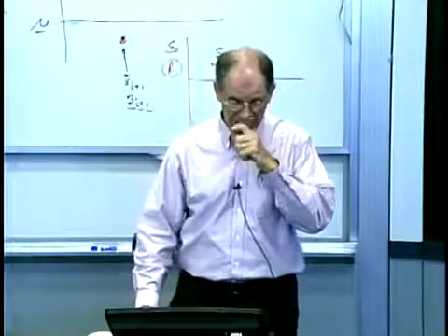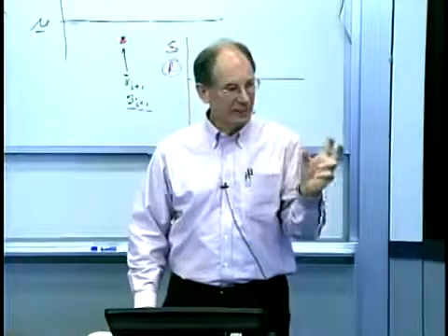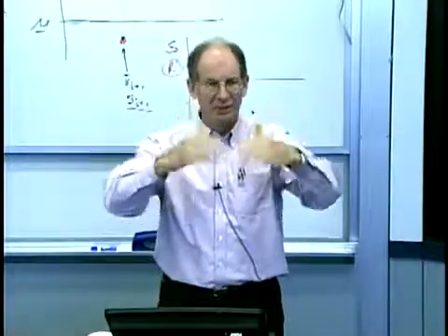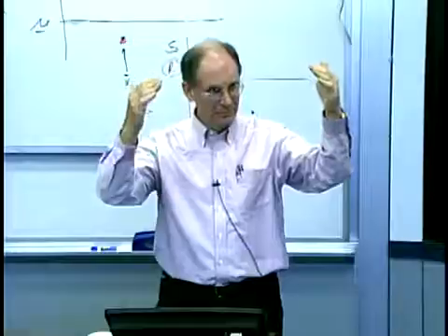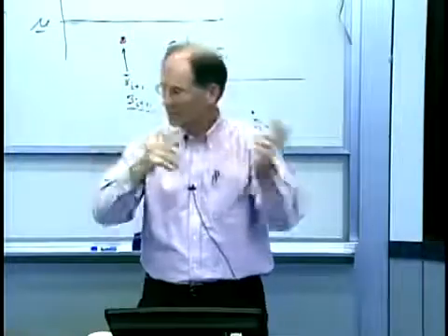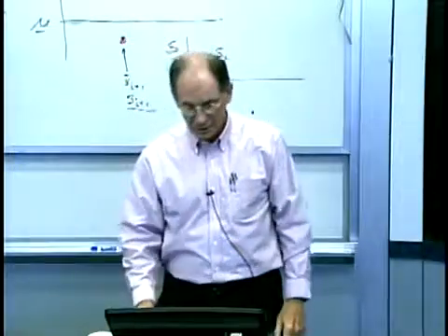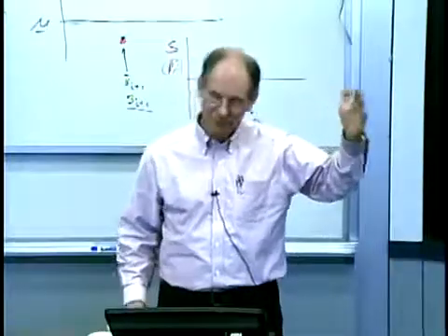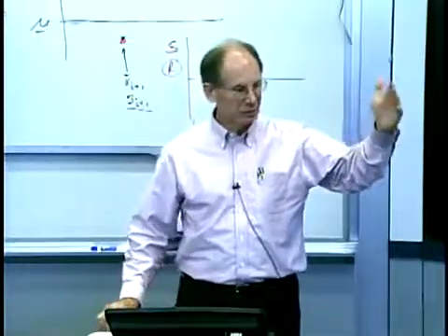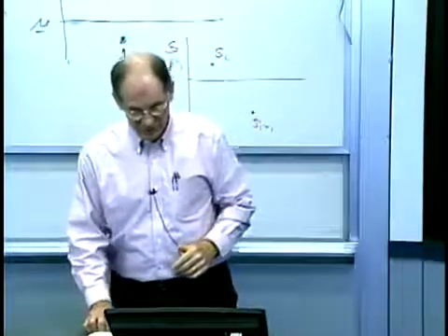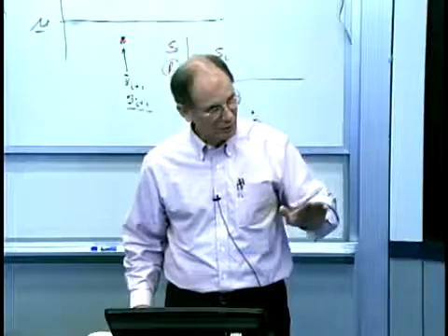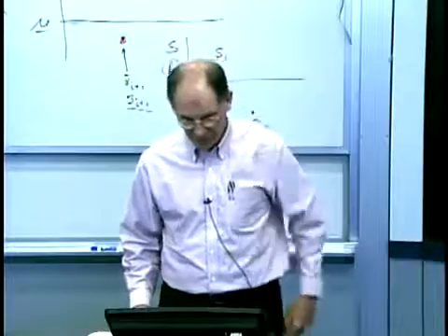Another one is runs of 8 or more points. Is there a run of 8 points that's always above the mean value? That's improbable. It's supposed to be random on both sides. Linear trends, of course: 6 points, and they've picked the numbers. It's a trade-off between sensitivity and resolution. 6 points in a consistent direction, always heading upwards or downwards.